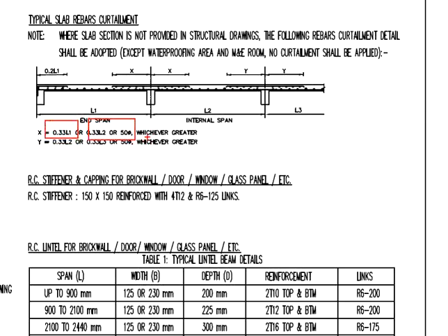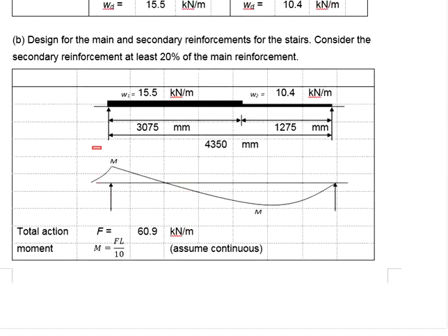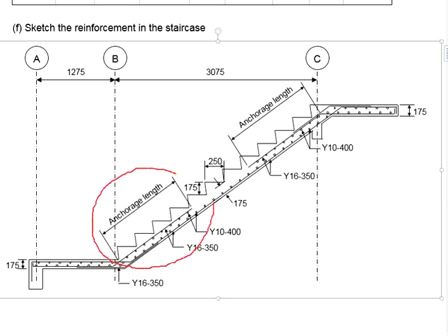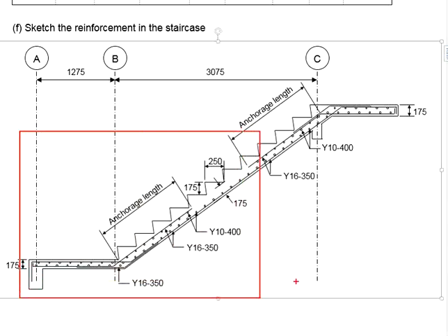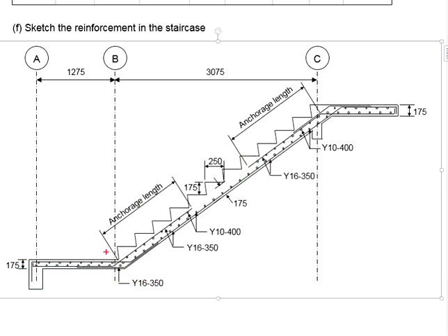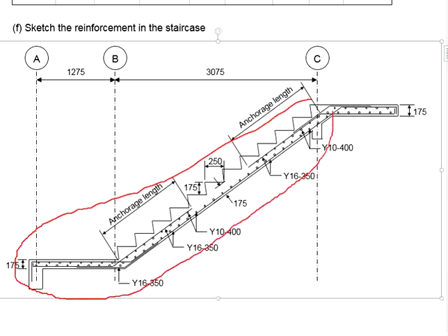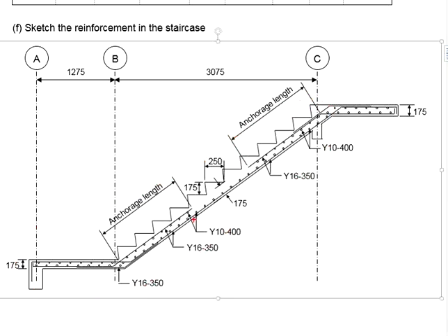Based on the proposed lengths, you choose the longest, and remember to check against the negative moment from the bending moment diagram. Although the reinforcement is sketched in this way, it is possible for this setup here. Your anchorage length might end somewhere here. Personally, I feel it is okay, since this acts as one single span. You don't have to always have the negative moment here.